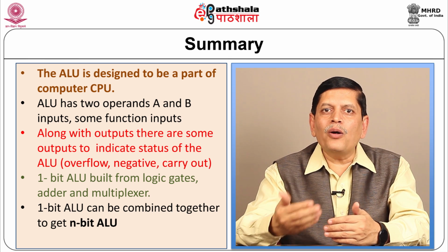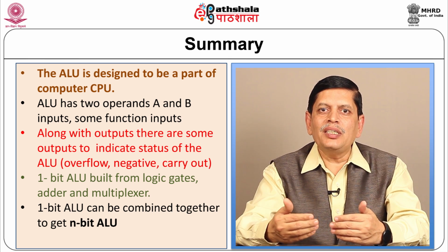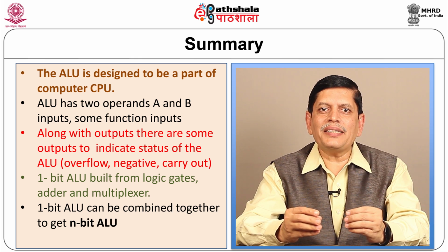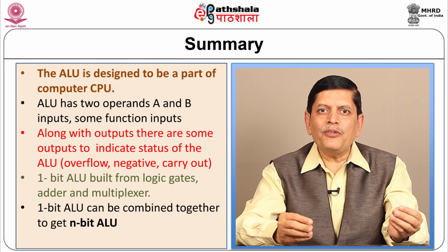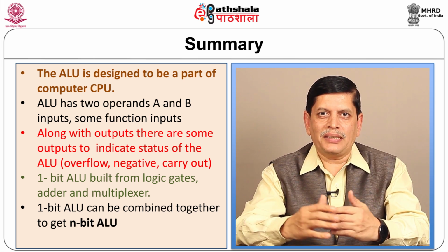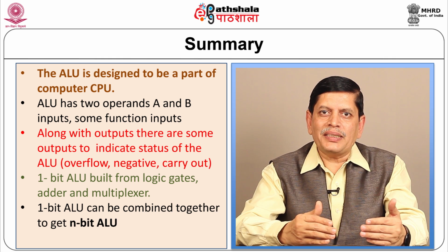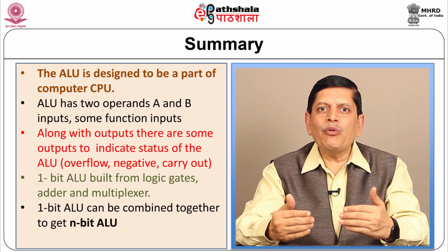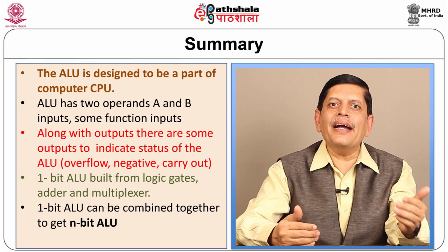Whereas in case of the arithmetic unit, we need to talk about how many arithmetic operations are to be implemented. And we have started with simple arithmetic addition, like simple 1-bit addition can be extended to 4-bit and n-bit operations. This addition operation can be extended further in such a way that we can even perform subtraction using an adder.